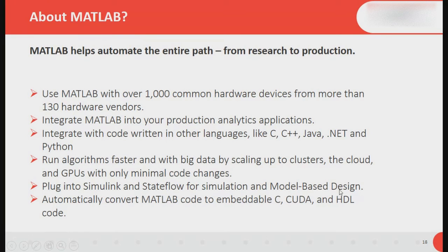Model based design means if you have to design any hardware or any application in real time, you can't directly launch that application in real time because it takes a long time to design it. Maybe you are not getting the desired output when you directly start designing in real time. So in model based design, you start from configuration, meaning what requirements are there for that, and then model in the loop, software in the loop, hardware in the loop, processor in the loop.